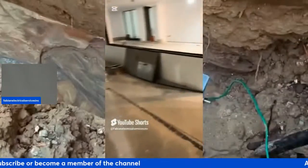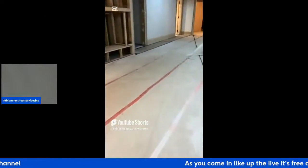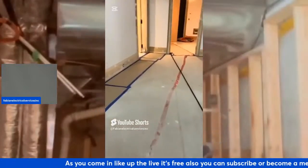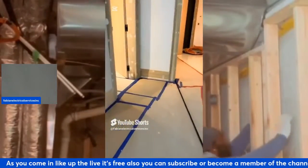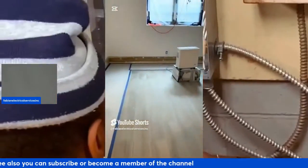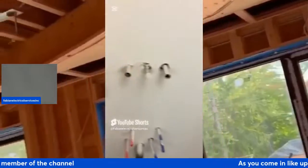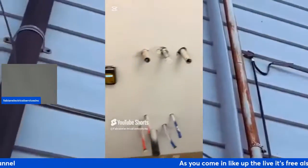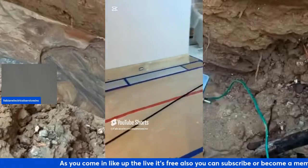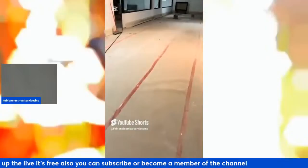Dishwasher is basically a straight connection. You also have anything else that's dealing with normal receptacles in the bedroom, in the garage that's attached to the house, even outdoor, also takes an arc fault receptacle. A lot of times motors don't take one, so you have your pumps. That's a straight up 20 amp or 15 amp, depending on what it's drawing.